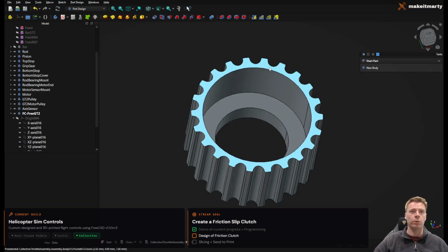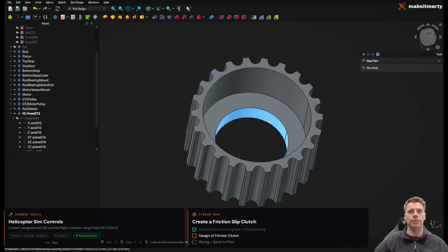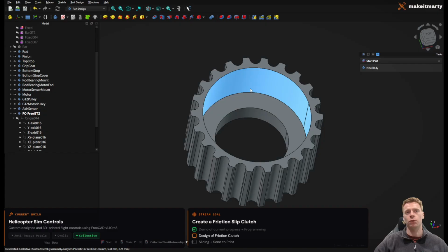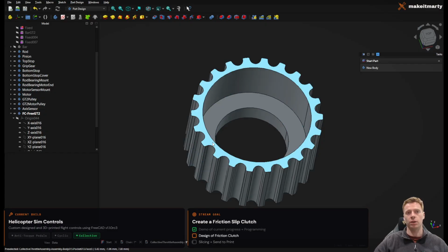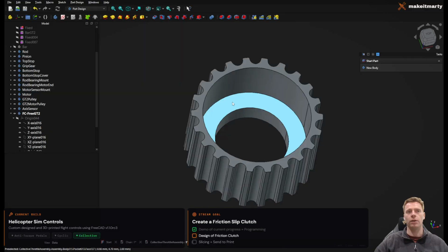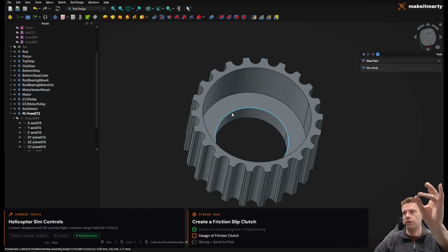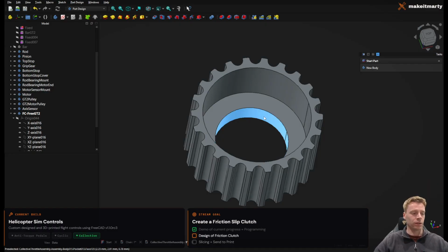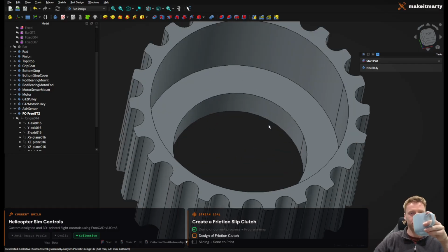Cool, so the bearing will essentially press into there, and any rotating stuff is handled by this cutout here. And that just accounts for the difference between our 7mm and our 5mm width of bearing. I guess what we could do is we could find a specific bearing that was perfect for this, but this will do.